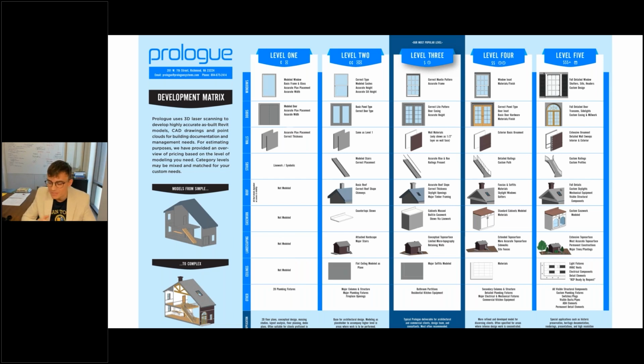You can always be more accurate. You can always have more detail. And so it's important to determine what's sufficient and not to waste resources exceeding that. Through all this, educate the client on what's possible. The laser scanner is not an X-ray. It works by visible line of sight. Help the client understand what will and will not be represented in the data.